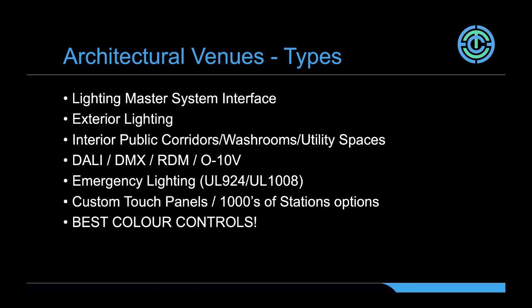where you can get quite the color swing. And when you get into venues where there's exterior lighting influence, so a venue that has a large glass atrium or large glass facades, and the ambient daylight from outside is going to be interacting with the interior lighting, it's super important that in our architectural systems we have that good understanding of color space. You don't get your pukey colors when the interior lighting design doesn't line up with what's currently going on outside with the sun. And the use of our daylight sensors and color temperature sensors can really help bring your vision for your lighting system to life there.